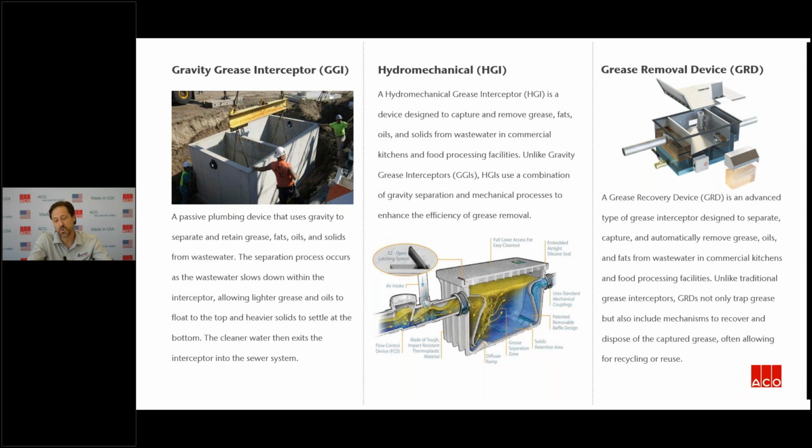We then have a smaller, more condensed technology called a hydromechanical, an HDI. That's mixing the gravity piece, but adding things of a more mechanical nature. So maybe it's baffles that help to separate the grease and water, allowing cleaner water to flow out one side and grease to separate out the other.